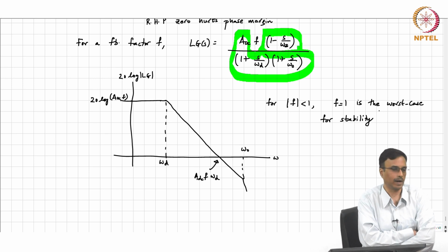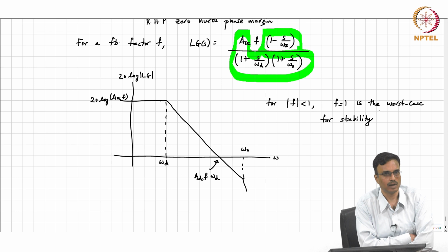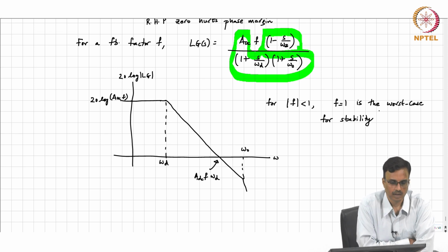If an op amp is not stable for unity gain feedback, that does not mean much if you are not going to be using it in unity gain feedback mode. Let us say you wanted a gain of 50, you only care that the phase margin of the closed loop system is sufficiently high for that particular gain.